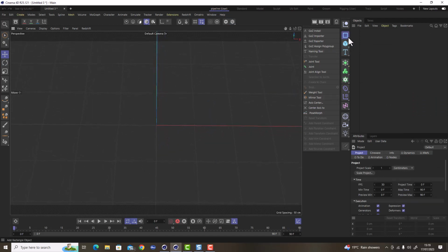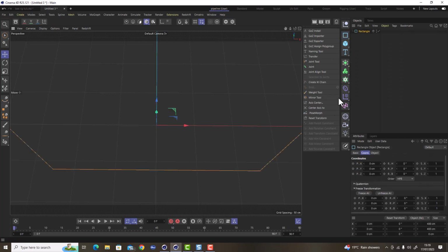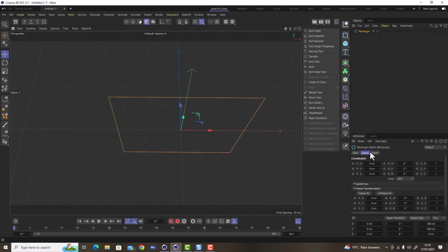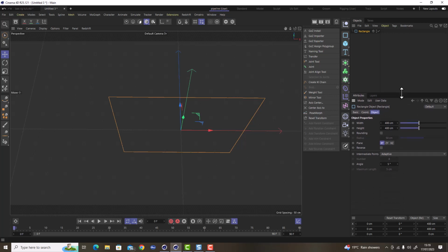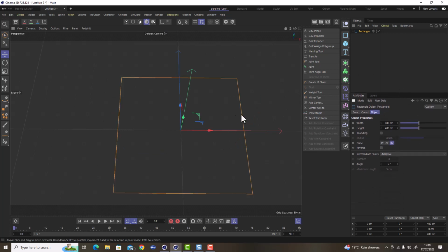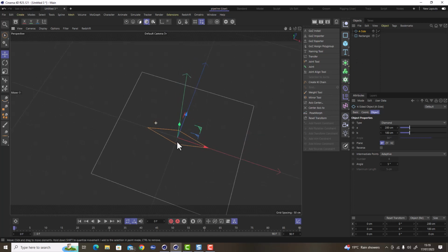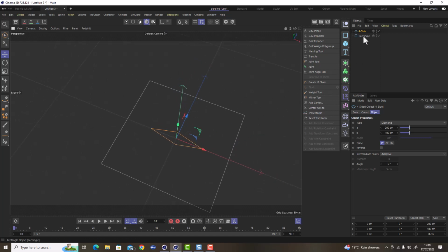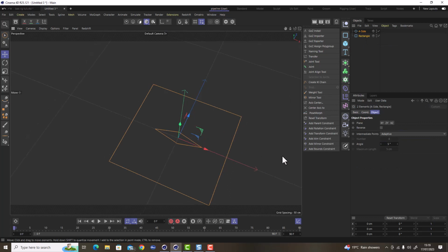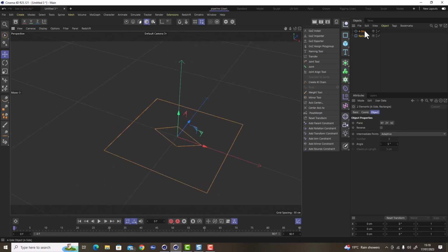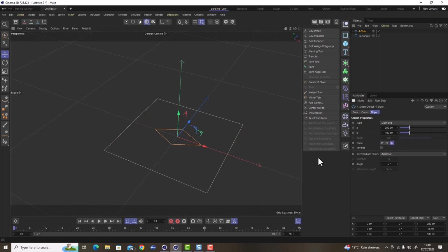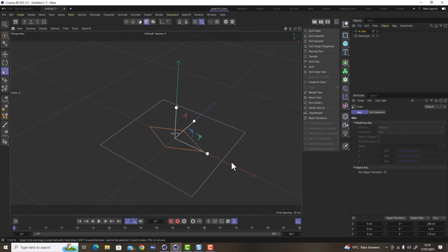So as an example here, we can go to our spline palette and you can see here that we've got all of these different shapes. Now I'm going to grab a rectangle, change its orientation in the object settings, and then I'm going to select, let's have a look, say this four-sided. And between these two I'm going to create something entirely different from it. And this is the beauty about using splines. Let's just select this and put it the same orientation. I'm going to scale this up.